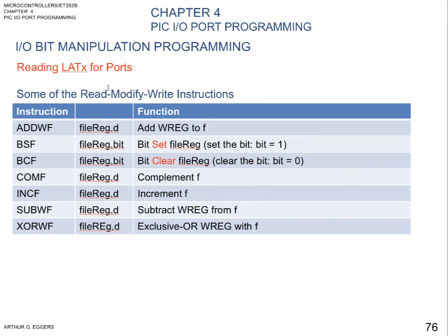In reading latches for the ports, you can see here that some of the read, modify, write instructions used, adding functions here for setting or clearing, the complement or an increment, subtracting, or doing an exclusive OR are all instructions that are used in read, modify, write executions.